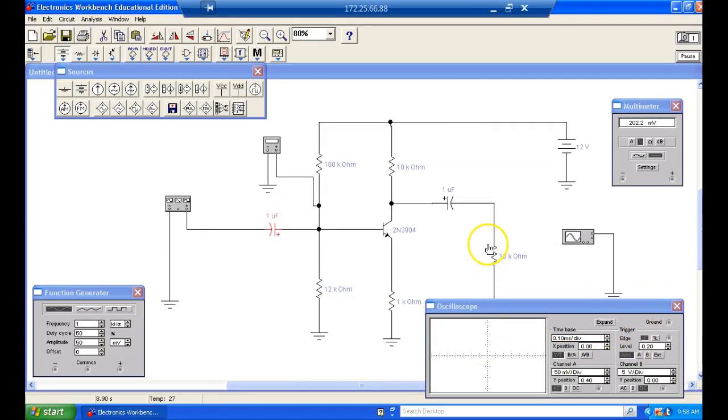So this resistor right here would be safe if we turned it off because the transistor would be cut off. So this should measure about 1K. This guy right here, these should be okay because they're not in parallel with anything. So you should be able to measure all the resistors inside a transistor circuit with an ohm meter. Right? Of course, we're going to get a bad measurement over here because this guy right here is leaky, right? So we can measure it, we isolate something, we check it. But we know it's either going to be this guy or this guy, right? That makes sense?